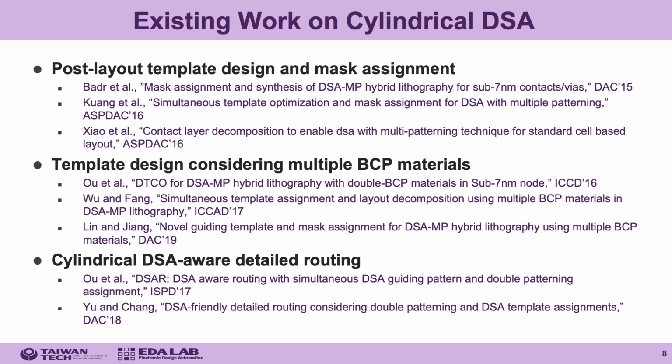There have been a few existing studies considering via fabrication with cylindrical DSA, which can roughly be categorized into three types. The first one is to perform simultaneous guiding template design for DSA and guiding template mask assignment for multiple patterning. The second group of papers additionally considers the design constraint induced by using multiple BCP materials. And finally, some DSA-aware detailed routing strategies have also been proposed.